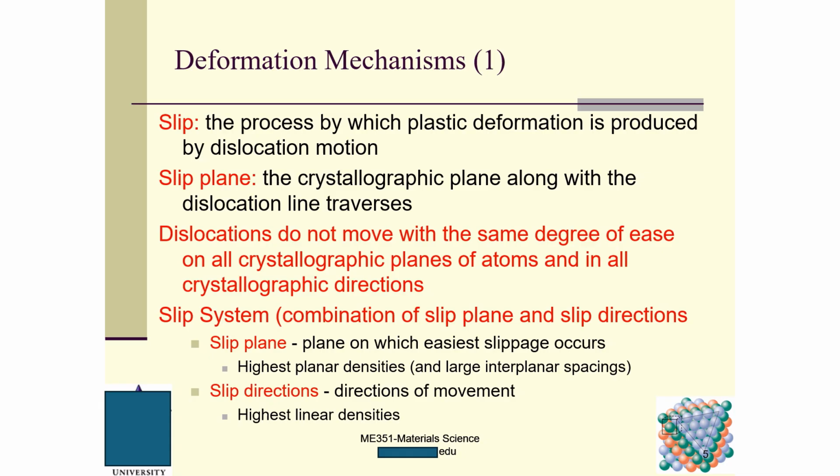This is a universal rule of energy minimization for any kind of physical deformation or physical phenomenon. Slip directions are the directions of movement, along the highest linear densities.